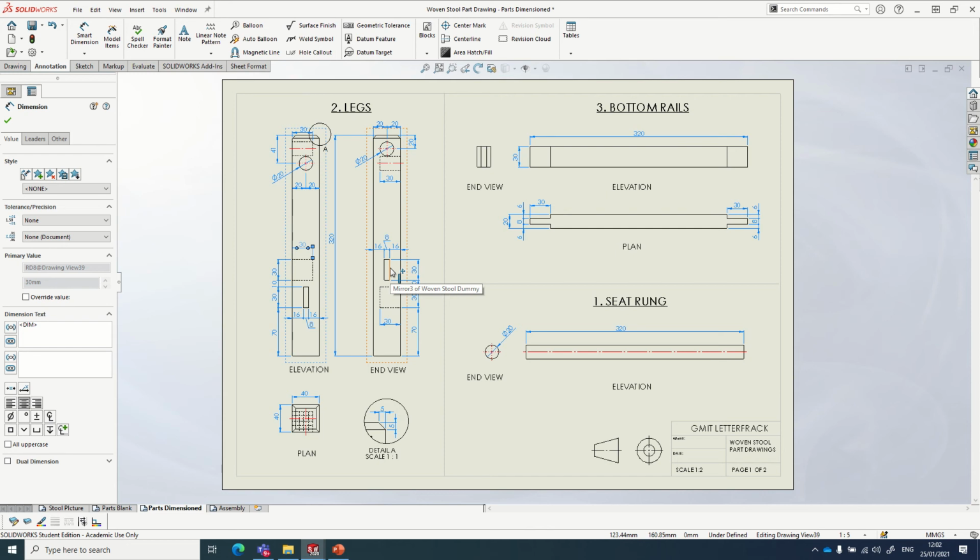In America, they use the ANSI system, and they use what's known as third angle projection. So the symbol for that is actually the same symbol, but it's reversed around. This will be on the far side. So to avoid any confusion, we reference this here, and we'll give an indication. We'll actually put up on Learn Online the dimensions for that, so you'll be able to draw that on your own piece. Aside from that, that is our main part drawings.